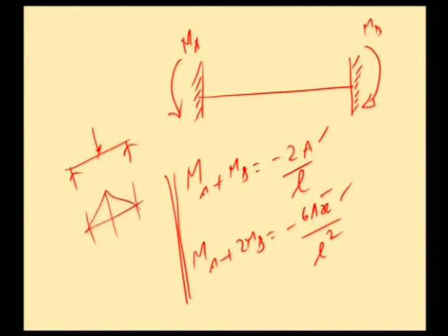We are very familiar with calculating the bending moment of simply supported beams. So, calculate or draw the bending moment diagram. This A represents the area of the free BMD. We call this the free bending moment diagram, free BMD. Free BMD means treating the given beam as a simply supported beam and drawing the bending moment diagram.